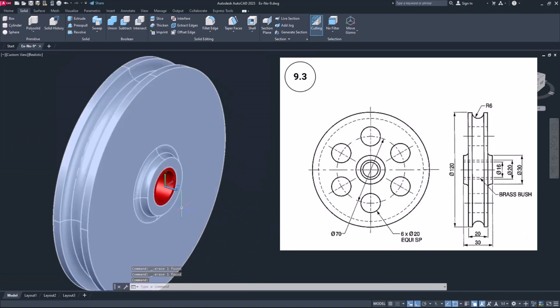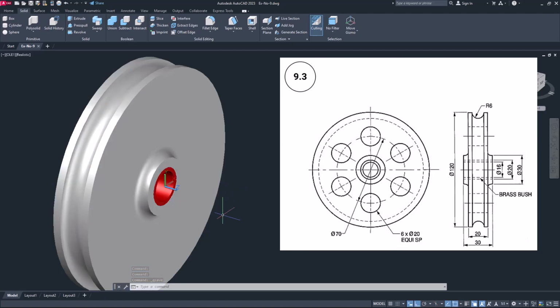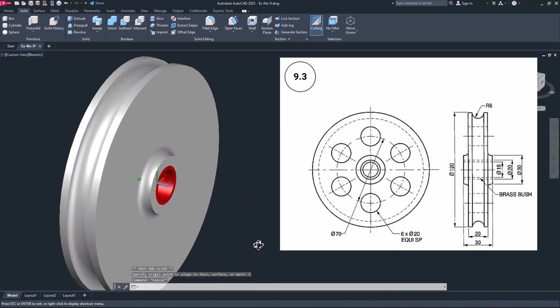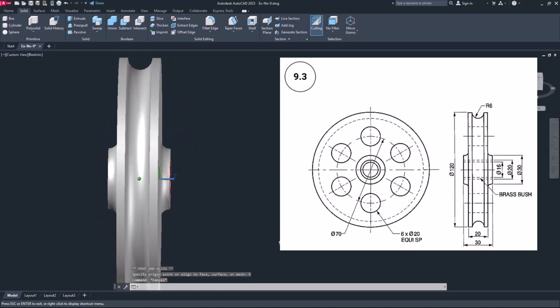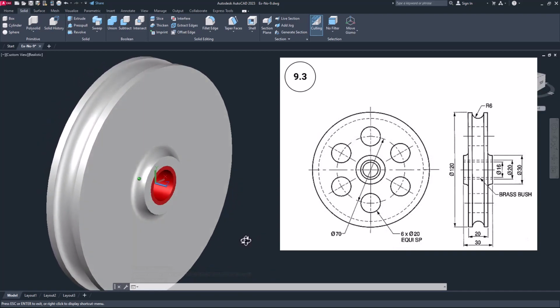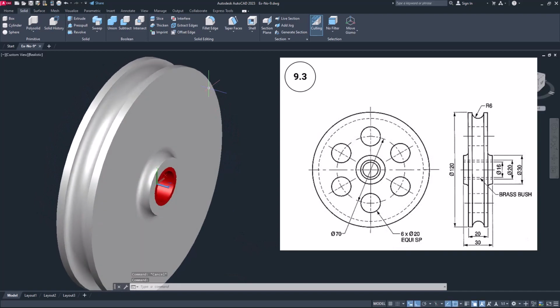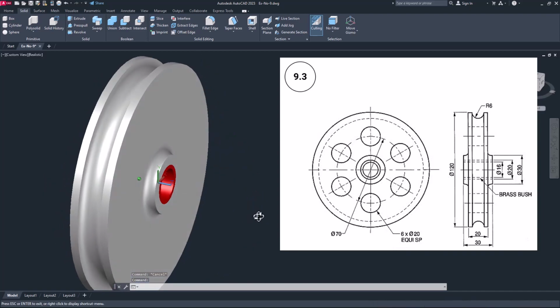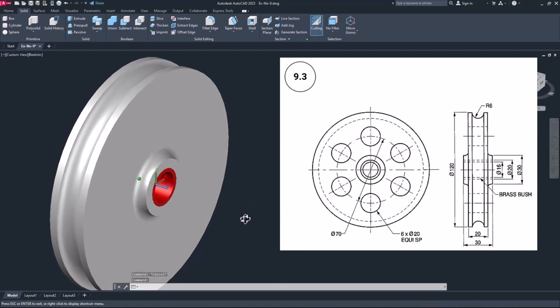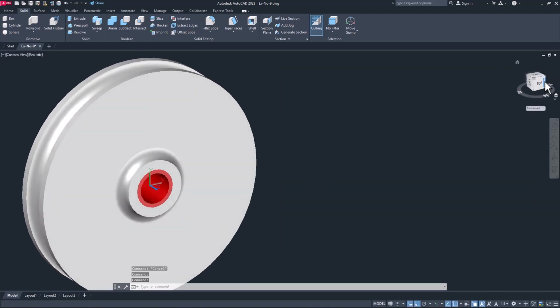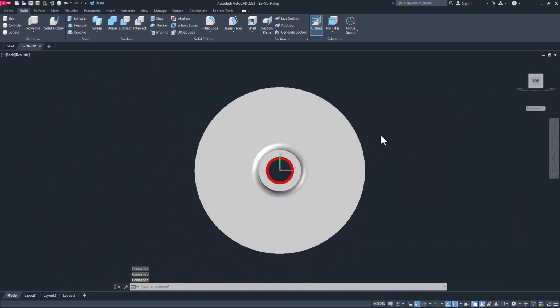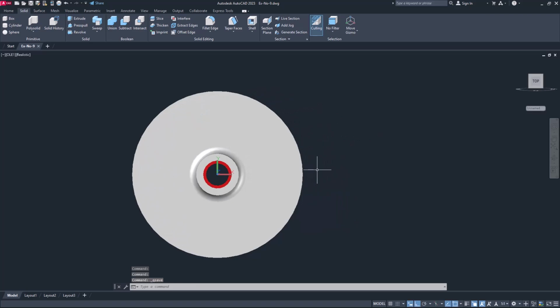Zoom out. Now let's try to draw the remaining circles. For this, what I have to do is move this by 5 mm. Okay. Just look very carefully. Otherwise, you can reorient this axis to that location, that is by using the circle of this larger wheel, right? But I simply displace it by 5 mm in the Z axis. Okay. Now let's choose the top point. Now save your drawing.